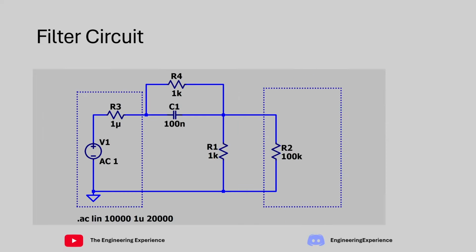Combining the two circuits that we've just looked at, we can end up with the following circuit. We have a potential divider with these two equations over here. If I set the value of those two resistors to 1K each, the output at DC will be equal to 0.5 volts over here, basically ignoring this load and ignoring the source resistor as well, because the impedance of the capacitor for DC is very, very high. So we can ignore this capacitor for the DC case.